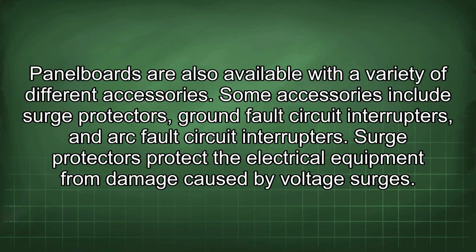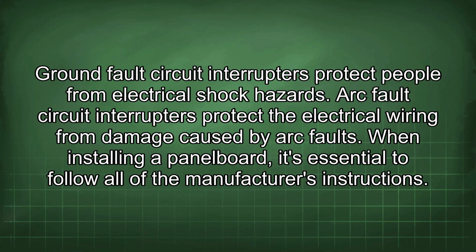Panel boards are also available with a variety of different accessories. Some accessories include surge protectors, ground fault circuit interrupters, and arc fault circuit interrupters. Surge protectors protect the electrical equipment from damage caused by voltage surges. Ground fault circuit interrupters protect people from electrical shock hazards. Arc fault circuit interrupters protect the electrical wiring from damage caused by arc faults.